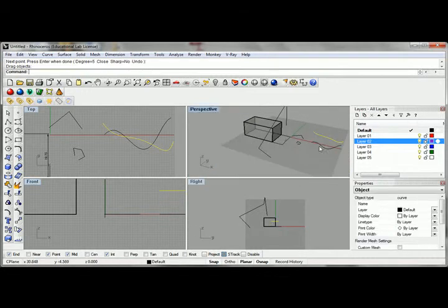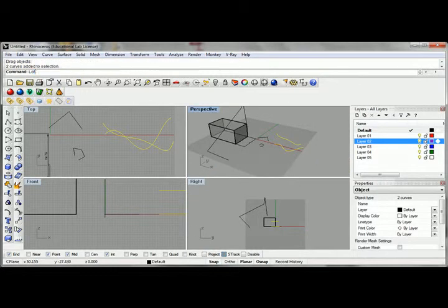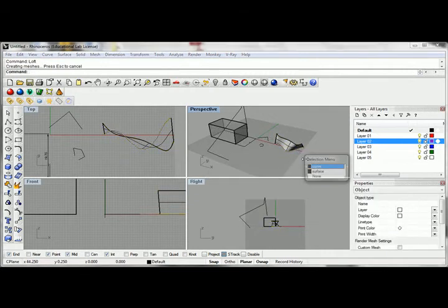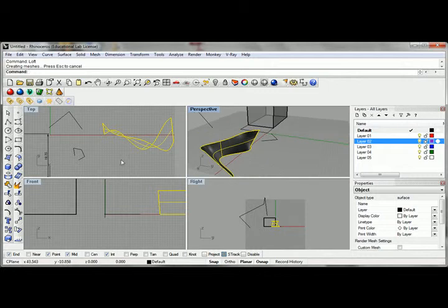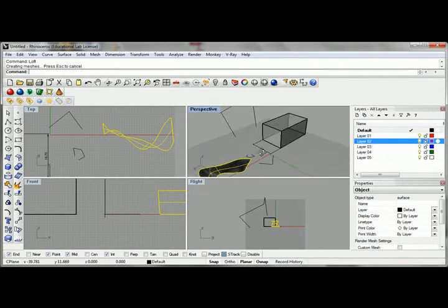view, and I'll pull this apart. We create some really simple surfaces, just by typing the loft command. We create surfaces from curves, and you can see how that's actually being driven. Beyond that, from surfaces, you can create solids, boxes, things like that. Like I said, Rhino is a surface modeler, not a solid modeler.